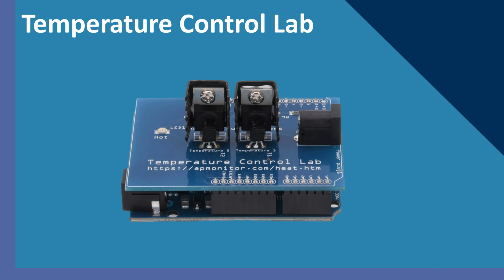For any control system, we need a sensor, an actuator, something that we actuate, and a controller. Here our computer will act as the controller. We have a heater that will be our actuator, will turn up or down, and we have our sensor that feeds back that information. It's actually a thermistor if we want to be technical. With these three units, we're able to control independently temperature 1 and temperature 2, shown here.